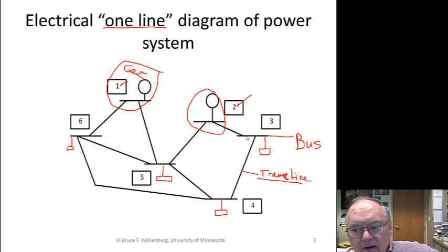You should go back and get notes for a more elementary course than this one, where we show how the per unit system can reduce the analysis. So we solve for one line, and we assume that there's a per unit impedance between the buses, and if we know the voltage, we can solve for the current, and then from the one line per unit system we can go back and calculate where the three-phase quantities are.